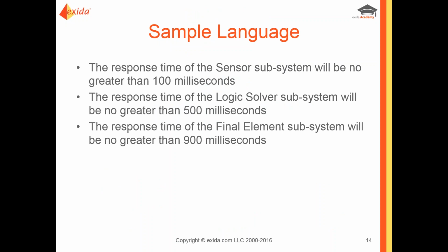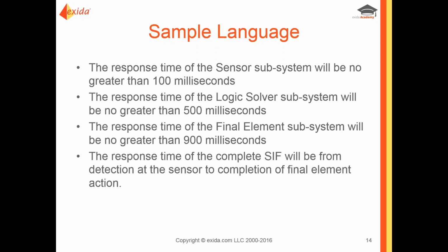One of the requirements we have for functional safety is to develop a safety requirement specification, and within that, defining the SIF response time is part of it. Now, the language that you see at the moment is basic language, but it's really directed towards the different subsystems of a safety function. It's good basic language to be a part of your SRS, but it does not complete the definition of SIF response time. The one area where folks most often struggle and is a little harder to define is what is the response time of the complete function.